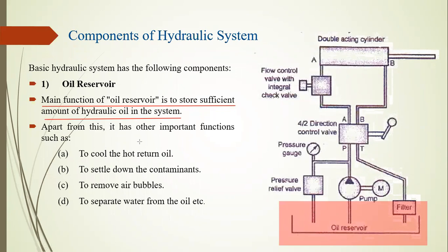What is the next function of the oil reservoir? Apart from this, it has other important functions, such as cooling the hot oil returned from the circuit. When we apply pressure on the oil, it creates pressure and also increases the temperature. So the oil temperature rises during working of the hydraulic system, and when it returns, the temperature is high, so it is necessary to cool the oil. That's also a function of the oil reservoir.